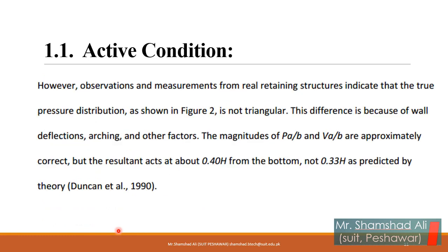However, observation and measurement from a real retaining structure indicate that the true pressure distribution, as shown in figure 2, is not triangular. This is because of the wall deflection, arching, and other factors.